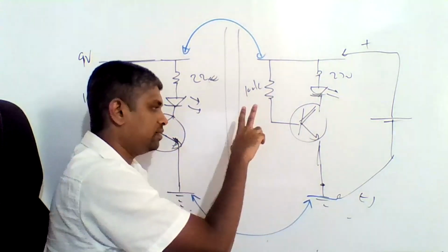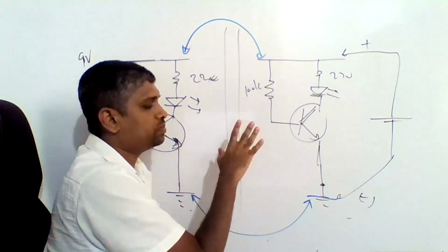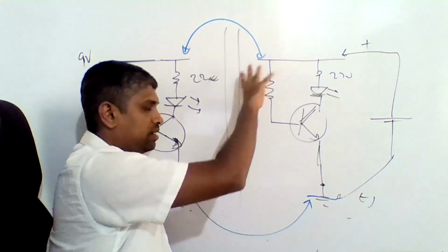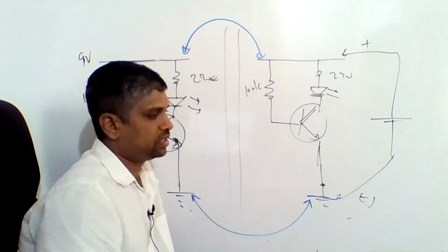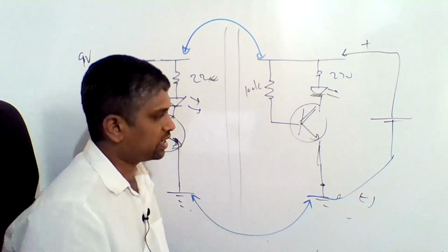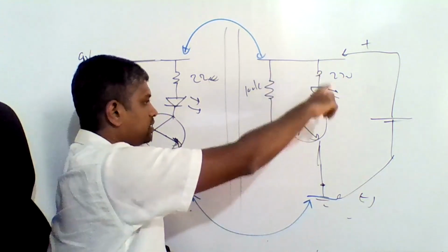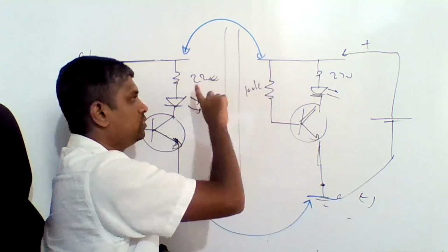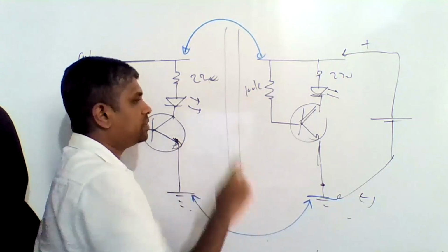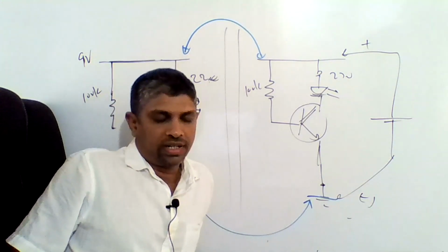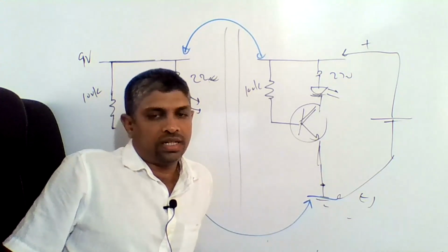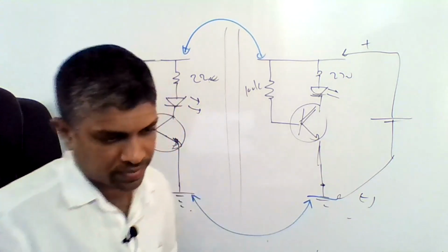If brightness is different, your circuit may not be identical. There may be some connection fault or component fault. Normally there isn't a component fault. If you have a misconnection, there will be two different brightnesses. You can use two different LEDs, no harm, two different colors, right? The brightness should come out about the same.